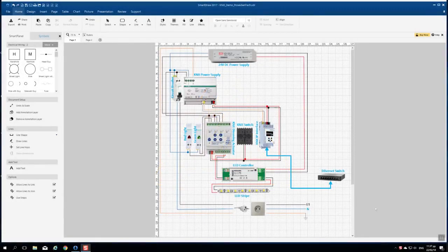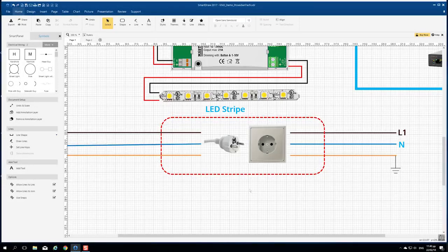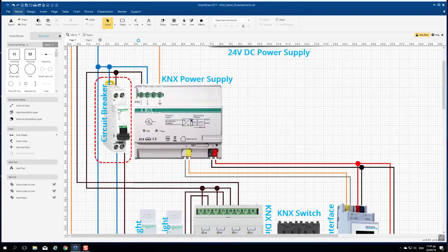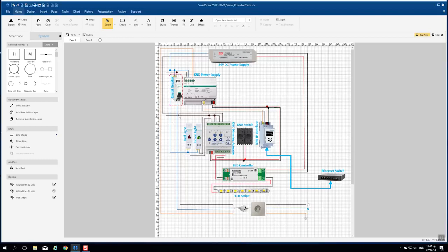Now, let's make some drawings in order to understand the devices and the connections. For our demo we'll need a plug with a cable in order to supply our devices with AC power: line, neutral and earth. One circuit breaker that can break circuit to line and neutral. As you can see, line and neutral from the plug are connected to the bottom of the circuit breaker.